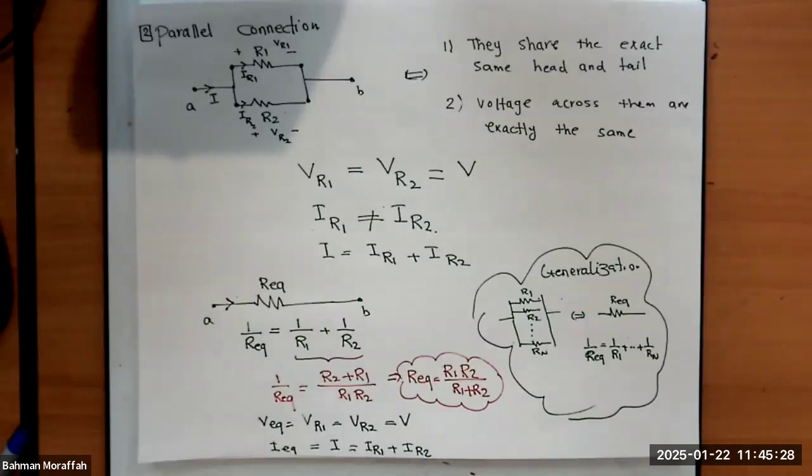To sum up what we talked about, if we have a bunch of resistors in series, what we're adding up is resistances. However, if we have a bunch of resistors in parallel, what are we adding? There is a name for it. We talked about it. Conductances. 1 over R is called conductance. So we're basically adding up all the G's. So we call it 1 over R equivalent, G.